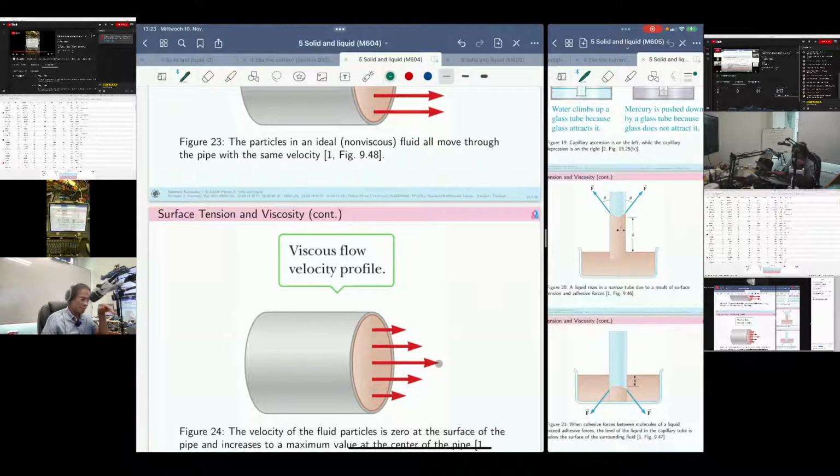Here in the middle of the liquid, it has only the friction between nearby layers of the fluid, so the friction is not high. When the obstruction is not strong, the fluid in this position is going to move very easily. So its velocity is going to be high at the center. When you are close to the center, you have less friction and your velocity is going to be increasing and increasing.